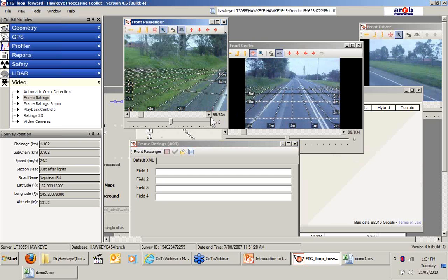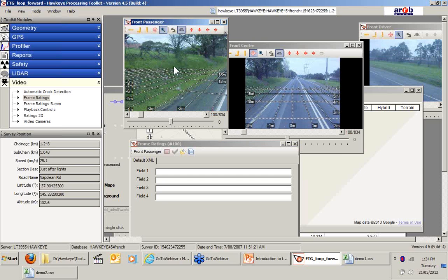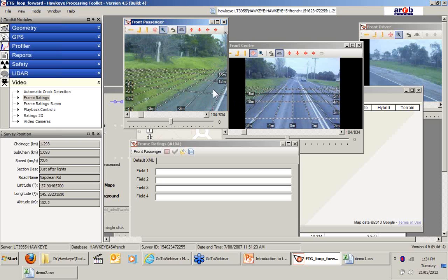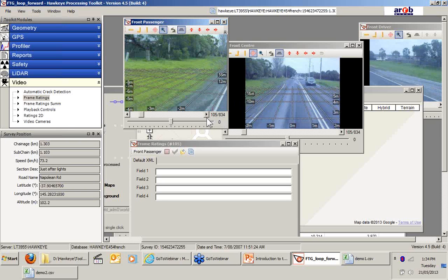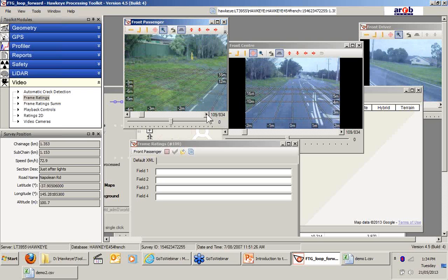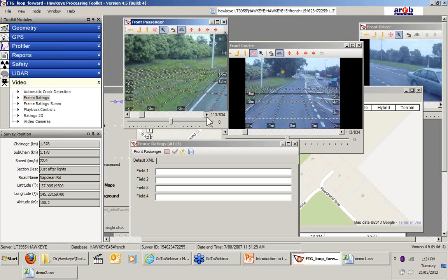Like that. But one thing is, these calibration planes can't tell if there's an embankment on the side there. So any measurements you do, it's making the assumption that it's the road surface, parallel with the ground itself, or actually on the ground. So when doing measurements, you do need to take them with a bit of a grain of salt.